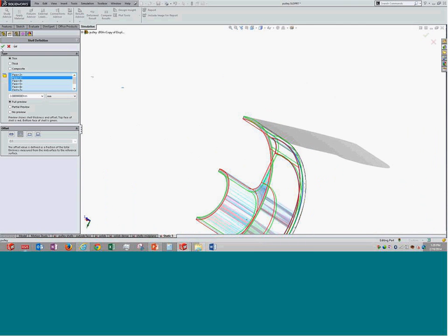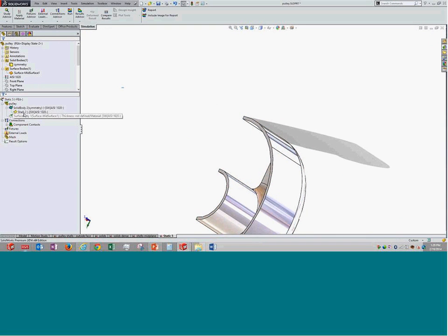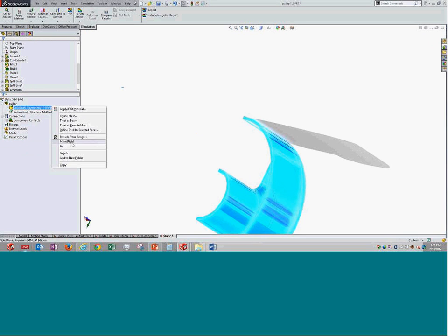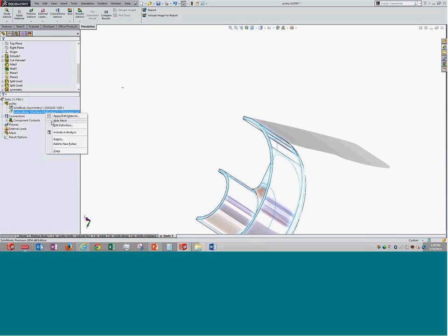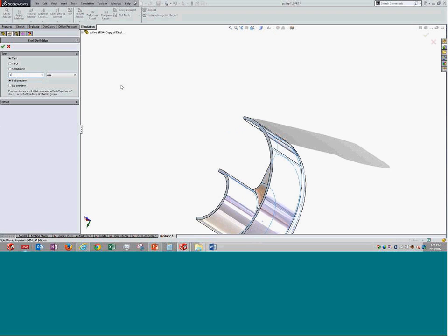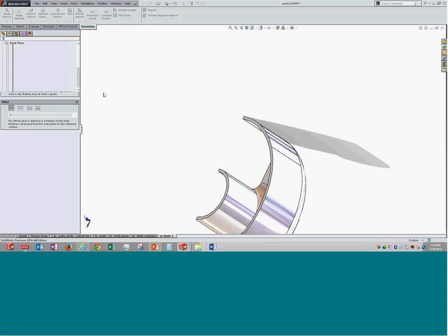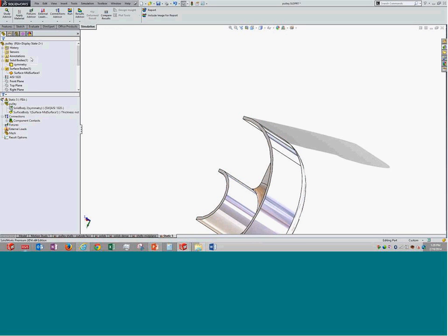So as I told you, the surface has already been created in the solid geometry. You can actually use it. The difference would be we need to specify the thicknesses over here. Over here we have the option of selecting the location of that particular surface, which I will not be showing in this particular example, but it is more towards a sheet metal part. Geometry which is a sheet metal part will be automatically treated as surfaces in section. You can use that option also.